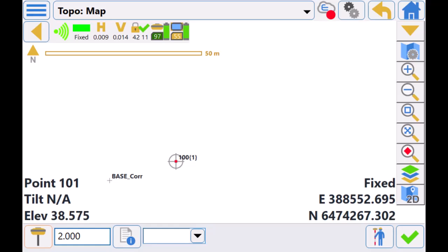Typically the GNSS weighted average feature will be utilized when a user wants to measure the same point at different times of day and get a good average over the same position to ensure it has the highest of accuracy, to remove any possible GNSS error at different times of the day.